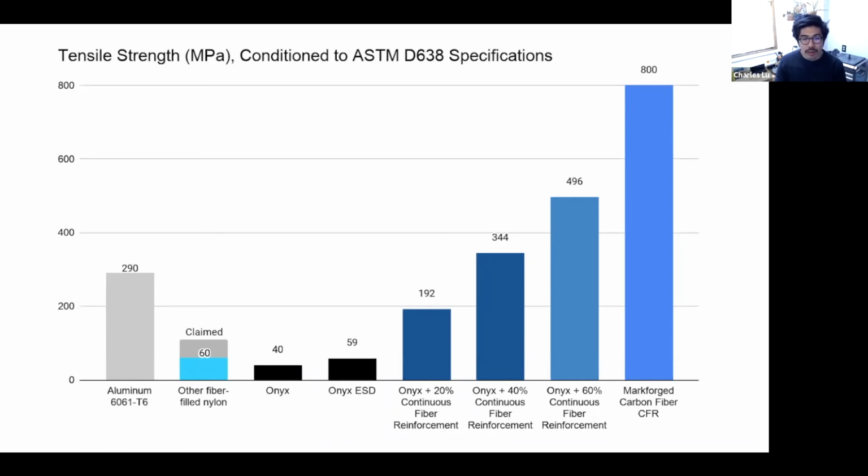You can machine parts after printing. Use a high-speed steel, an uncoated cutter. I would say go at high feed. Don't go too fast because then you'll heat the material up. So just be mindful that you can burn or warp the material. So lots of little short cut passes. That said, there is carbon fiber in the material, so be careful. If you're going to mill something, be aware that there will be dust particles that come out of it. So make sure that you're using some cutting fluid that will be able to carry that away without letting it go into the air.